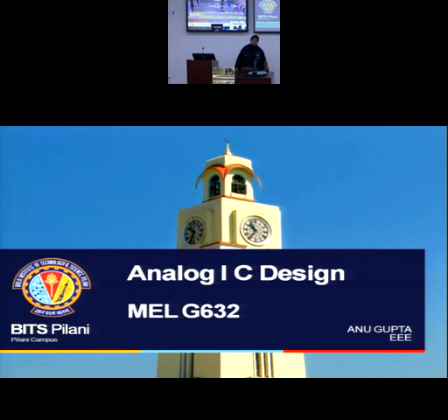But now what happened recently is that the moment you have off-chip computation or off-chip communication, one chip to the next chip, there's a delay involved, a lot of delay. So to make systems very fast, my chip can be operating at a very high rate, but because of these off-chip communications that speed was getting limited. Because off-chip communication cannot be very fast depending on the capacitive loading that comes due to IO pads. As a result, people thought, let me do away with off-chip communication. Let me bring everything into the same chip. And that is where the SoC starts coming into the picture.